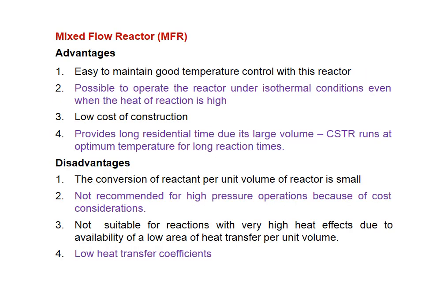Some of the advantages and disadvantages of MFR or CSTR we can take. First, the advantages: it is easy to maintain good temperature control within the reactor, and it is possible to operate the reactor under isothermal conditions even when the heat of reaction is high. It has low cost construction and provides long residence time due to its large volume.